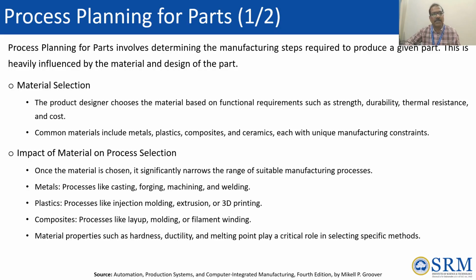That is what process planning, because it depends on the design. Whether knurling is there, chamfering is there, facing is needed, step turning is needed, whether we need grooving, depends on what kind of material. We need to choose the process plan, the sequence of operations. That sequence of operations we are planning is the process plan.